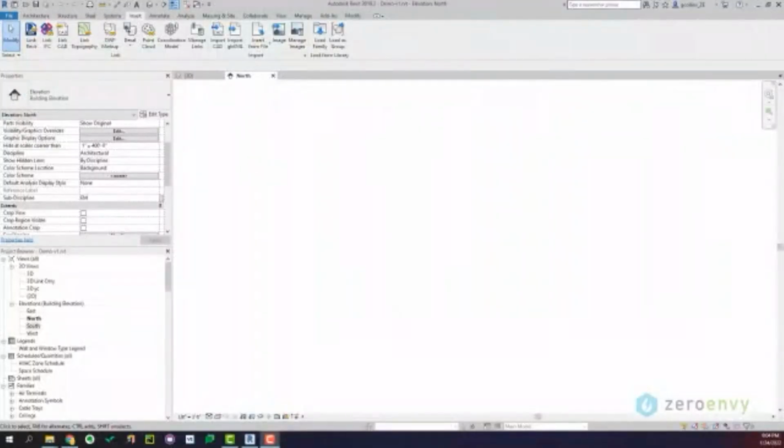And in this video, I'm just going to walk you through a quick demo to show you guys all the steps and what it takes to complete a model in Revit. And then I hope you guys can have a better idea on how the entire workflow looks like. So yeah, let's jump into it. So the first step is to link an architectural Revit model as a background in our blank Revit file.